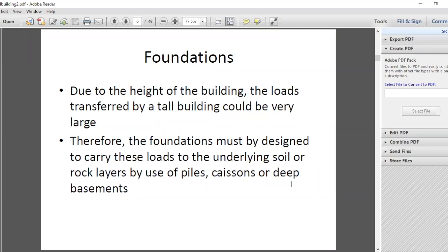But when it comes to the kind of the geological formations in main city like Colombo, you'll find to a certain extent we are lucky. The reason is bedrock can be reached within 20 to 30 meters in most of the locations, and certain places it can go up to about 40 to 50 meters as well. So one of the advantages, we have good firm rock strata on which the buildings can be located.